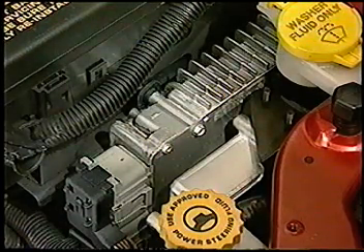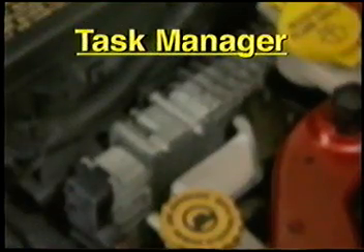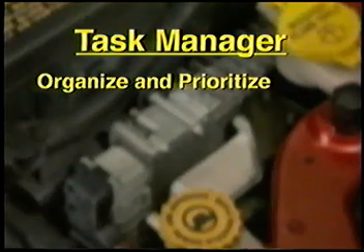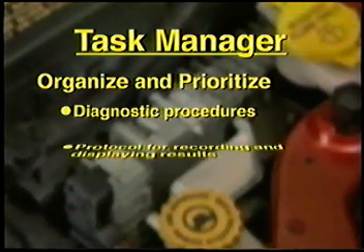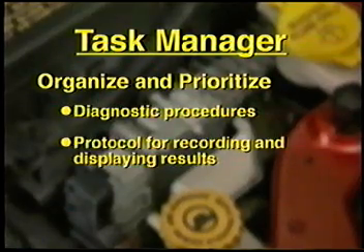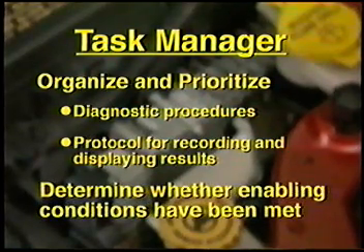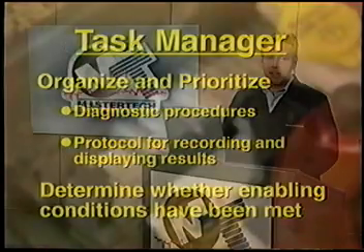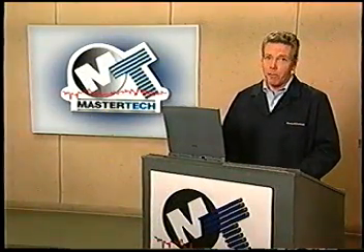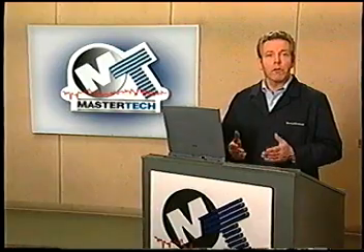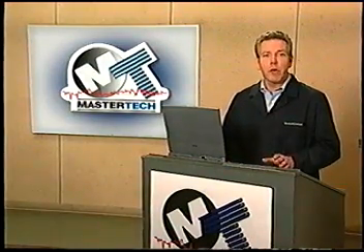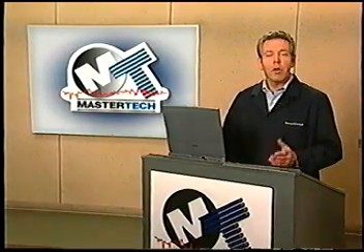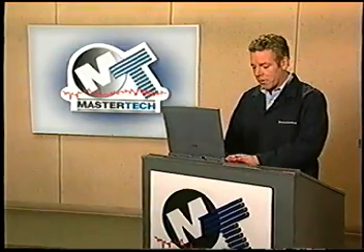Software in the PCM, referred to as the task manager, is used to organize and prioritize the diagnostic procedures and the protocol for recording and displaying the results. It also determines whether enabling conditions have been met in order for each monitor to run. In a sense, it's the traffic cop of the onboard diagnostic system. Some conditions may prevent a monitor from running in order to avoid a false failure. These are referred to as pending, conflicting, or suspending conditions.